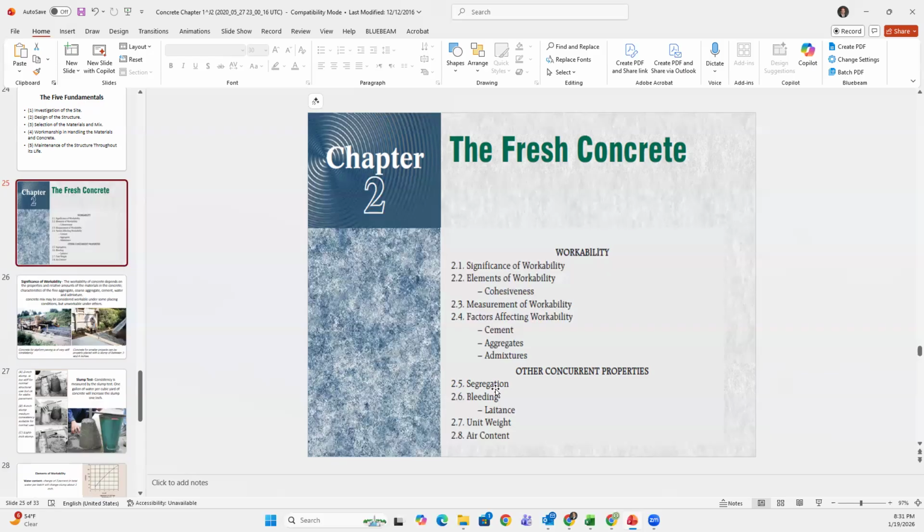A good concrete, when you finish, shouldn't bleed. It shouldn't have too much water in it. I'll show you pictures, but the terminology of bleeding is important. Bleeding is where you have smoothed the concrete, you're towards the end of it, and you see water surfacing, water coming to the top.